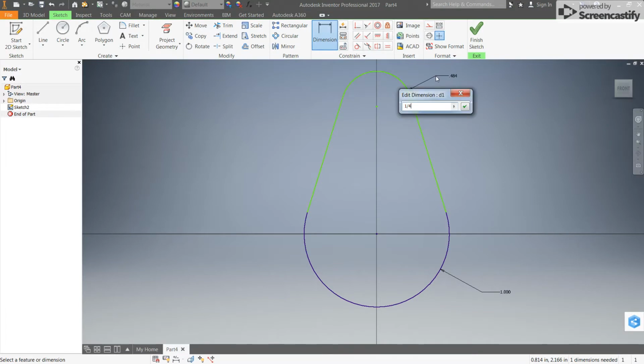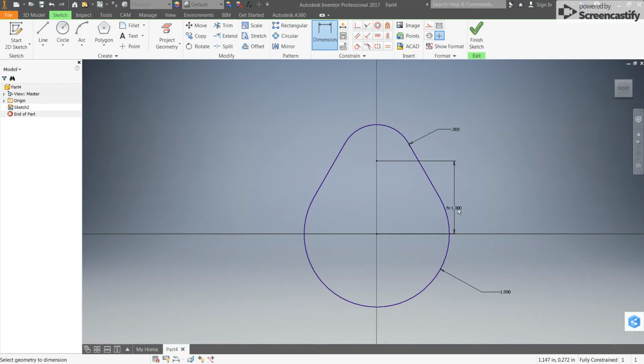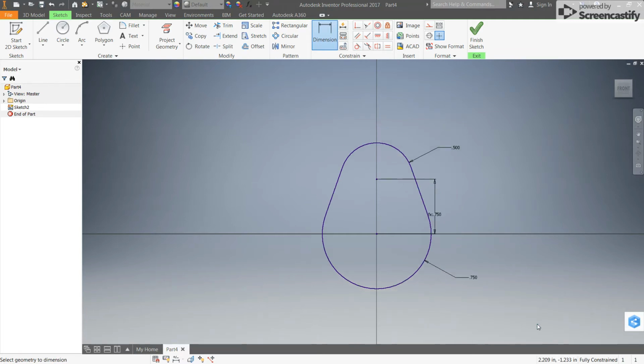Same thing, this is supposed to be 1/4 times my nominal, which is 2. And I can do the same equation here, but I know this value and this one right here are going to be the same. They're both supposed to be half my diameter. So I can just go ahead and click on this. This one has a name, it's D0. So these two are going to be the same. And you can see function 1 inch. So if I were to change this, one changes too. I'm going to put this back because I really do want it to.